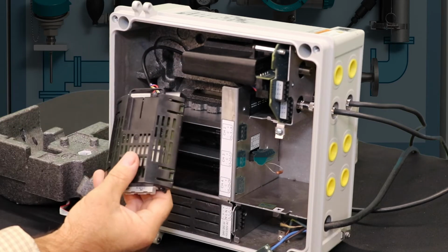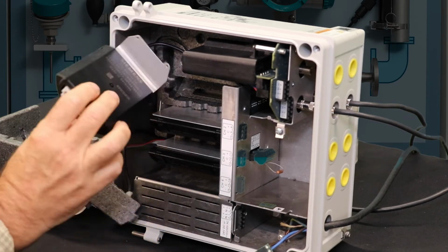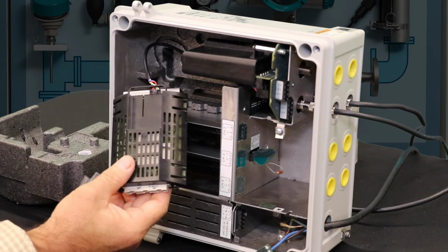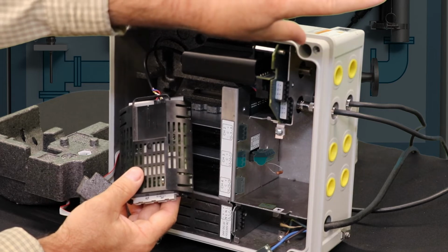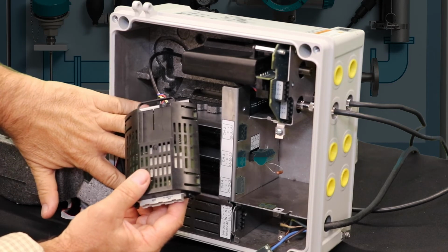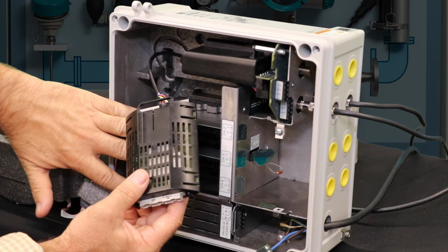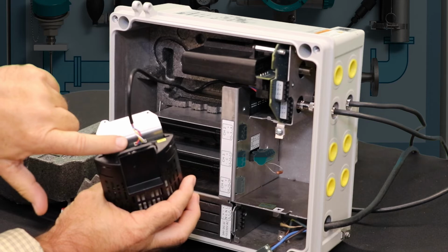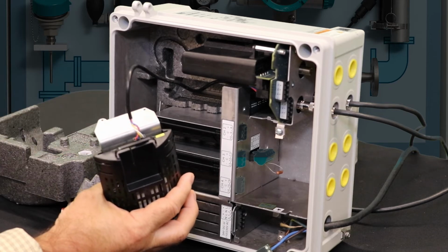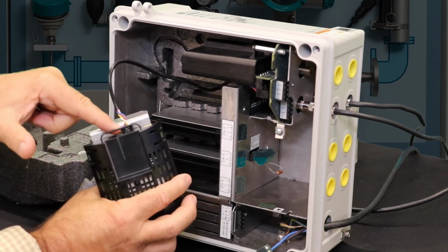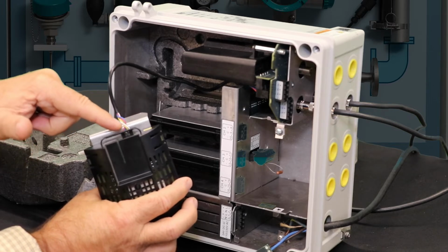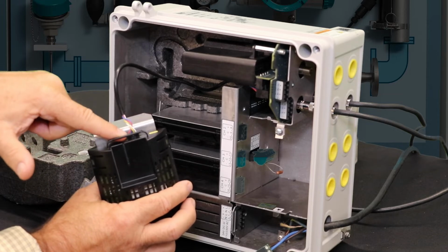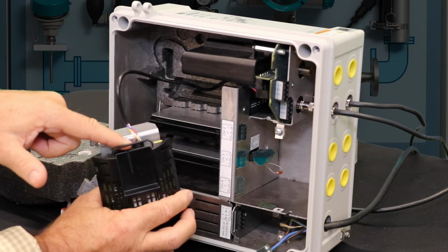And the last one is the barrier cassette. And this is what acts as isolation and protection between the outside world from the transmitter and the rest of the transmitter internally. And if you notice, the other end of this cable gets plugged in here at the top of the cassette. And you'll also want to check and make sure that this is not loose if you have that DSL error code that we saw.